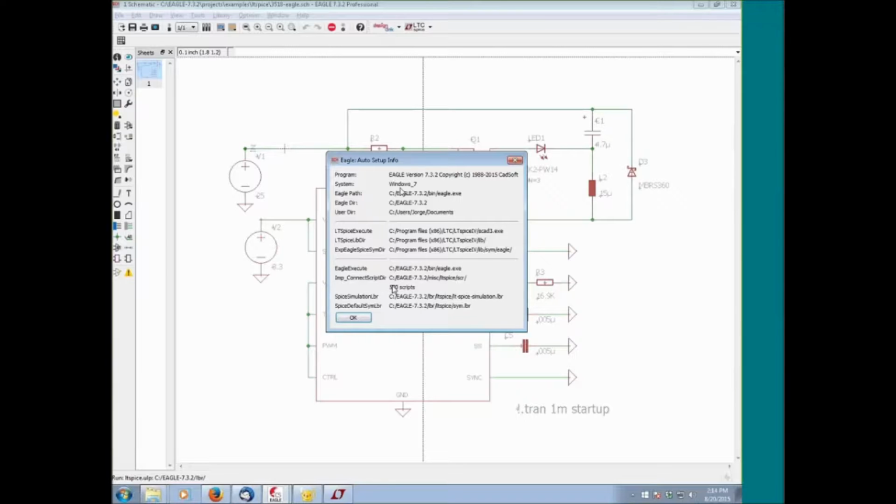This right here is what currently makes the LTSpice UOP not compatible under the Mac or Linux operating system. All of these paths are hard-coded into the UOP. So if you alter where you're installing LTSpice or you make any other variation on that, then the UOP won't be able to find it. And that makes this setup a little fragile. If things aren't set up in a way that the UOP expects, then none of the interface can work.